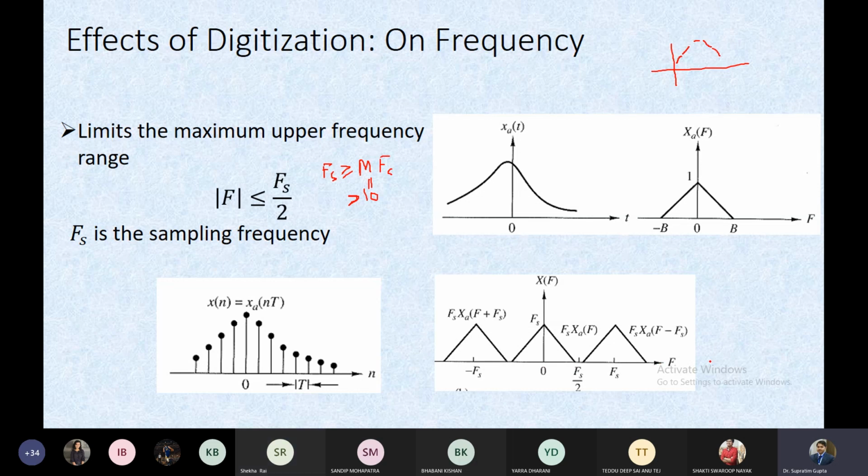So what is the implication of this? We need to select this particular band. For that, we require an anti-aliasing filter prior to the ADC. Whenever we apply an anti-aliasing filter prior to the ADC, it means we need an analog filter. How can we employ an analog filter? There are several ways. One is using only capacitors, inductors, or resistors, so passive elements. Another option is using active elements, the op amps. With that, we eliminate these frequency components and keep only this one.